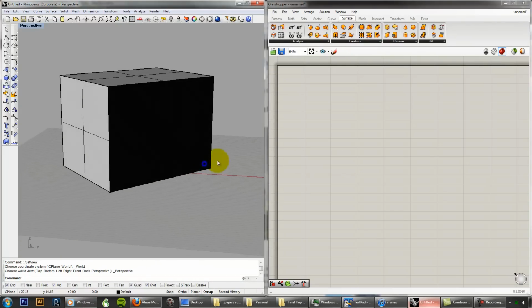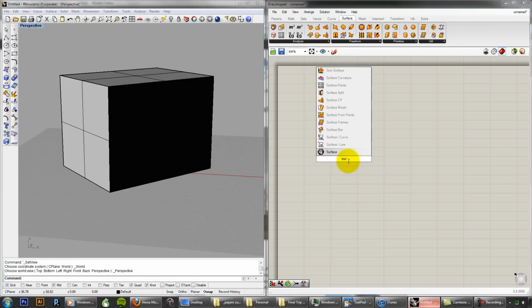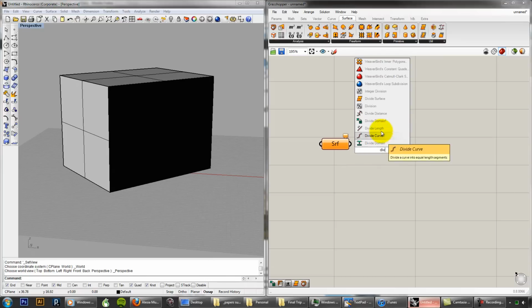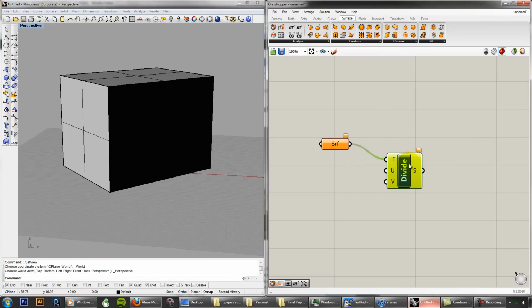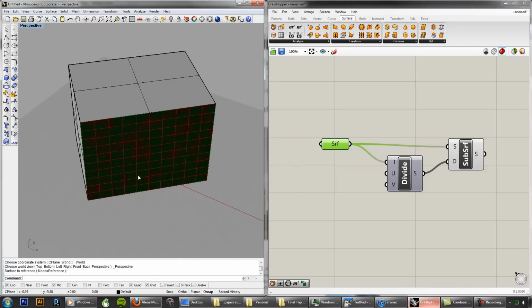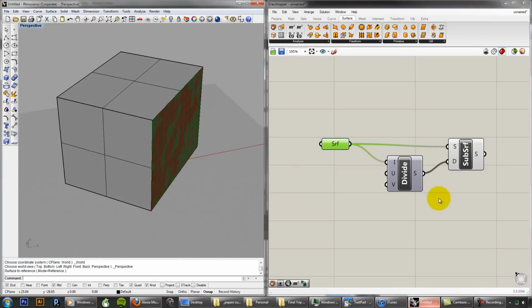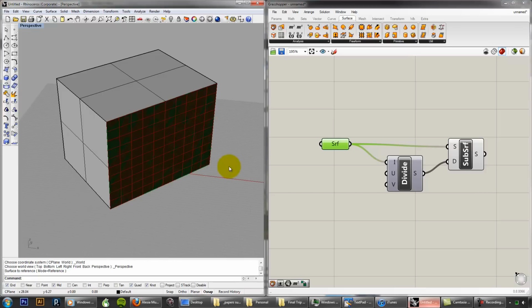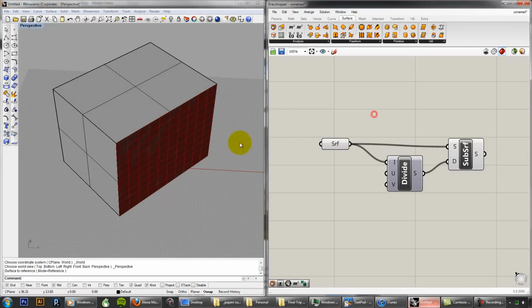Right away, an easy thing we can do, if your process uses it, is to reference the surface directly and divide that surface. Right, so we can go into Surface, Divide Domain, this old pattern. Okay, so trim. And if you do that, you get a parametric division of that surface that applies to the angle. The problem is that if you want to do anything with this that involves extruding from it or positioning something, you need to get a different coordinate plane.